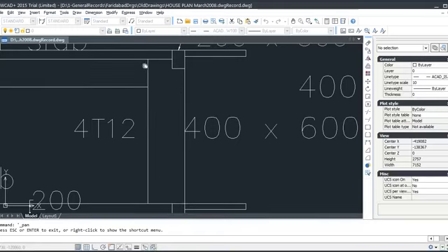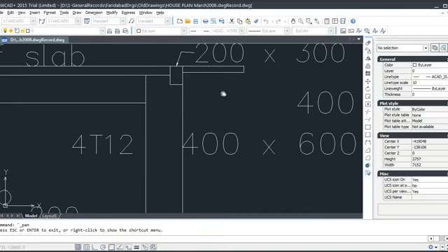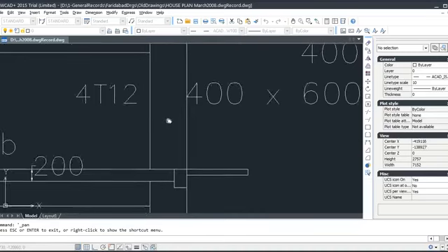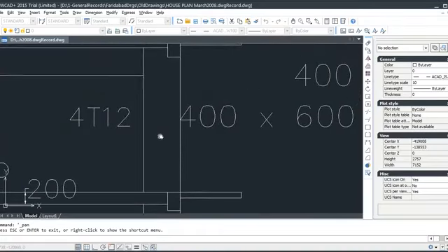If your pump is here, I mean a concrete pump, the pump boom, this pipe boom of a mobile pump or whatever pump you have, comes down, and if your pump pipe boom goes up to here, and this portion is a 1.5 meter height, then your pipe is authorized to drop concrete from a height of 1.5 meters.